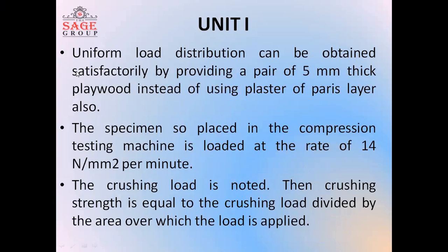A uniform load distribution can also be achieved satisfactorily by providing a pair of 5 mm thick plywood instead of plaster of Paris. That means a wooden plank of this size is placed on the stone so that the load can be distributed uniformly on the stone.